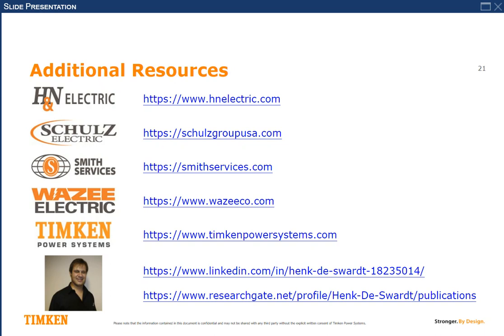Things like the shaft, most shafts have a design life, which the OEM would be able to give to you, but it's normally decades. So how many times can I repair the machine or rewind the machine? I don't know, 20, 50 times, whatever. As long as you make sure that you do the measurements to qualify the condition, you can repair it as many times as you like.